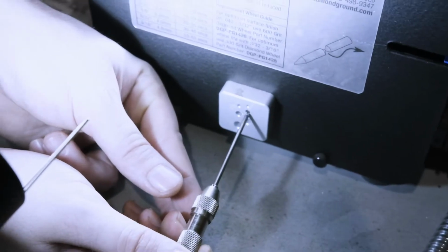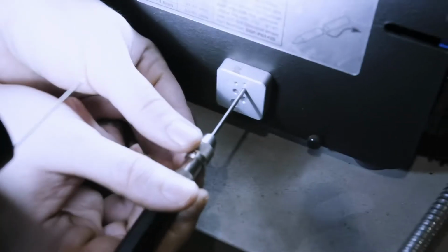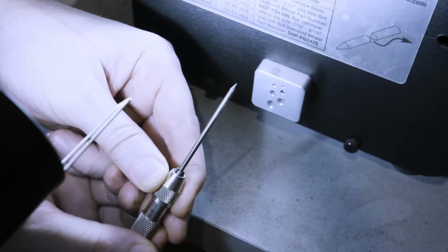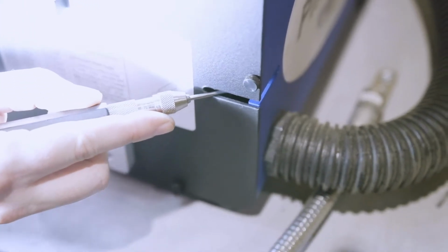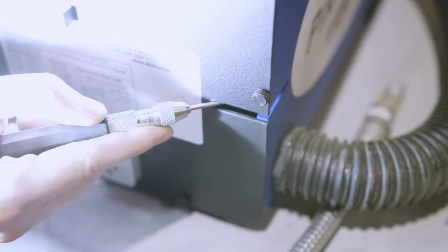There is also an area to blunt the tip as desired, and if you have a lot of crud on your tungsten and you can't fit it into the appropriate hole, there's a cutoff wheel which can be used to clean the tungsten or make a whole new tip if necessary.